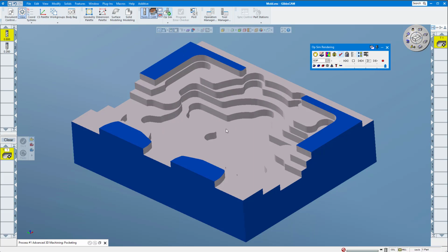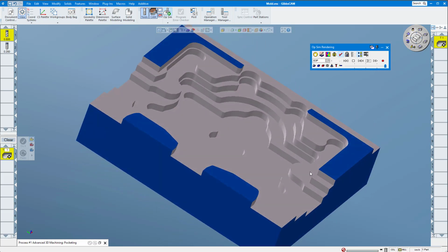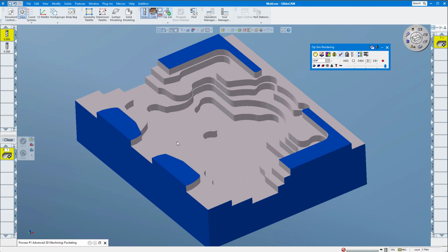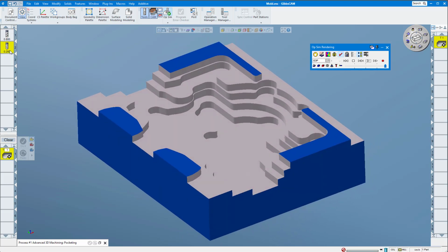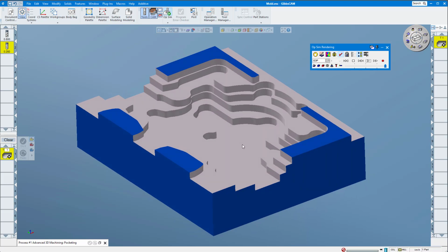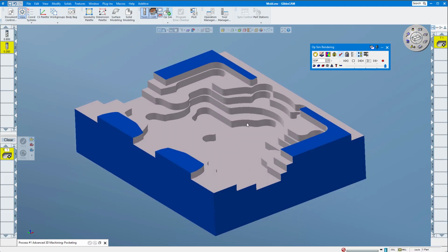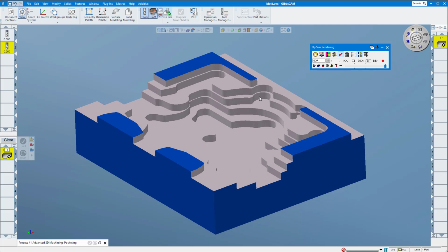Geez, we all wish our machines worked that fast, right? So then there's that roughing that I was talking about. So, this is great. The problem is, with this 1/4 inch ball mill that I really want to do that step over with, it's really asking that quarter-inch cutter to hit these steps, these really high steps, and we're going to get cutter whip, maybe even break the cutter. It'd be terrible.